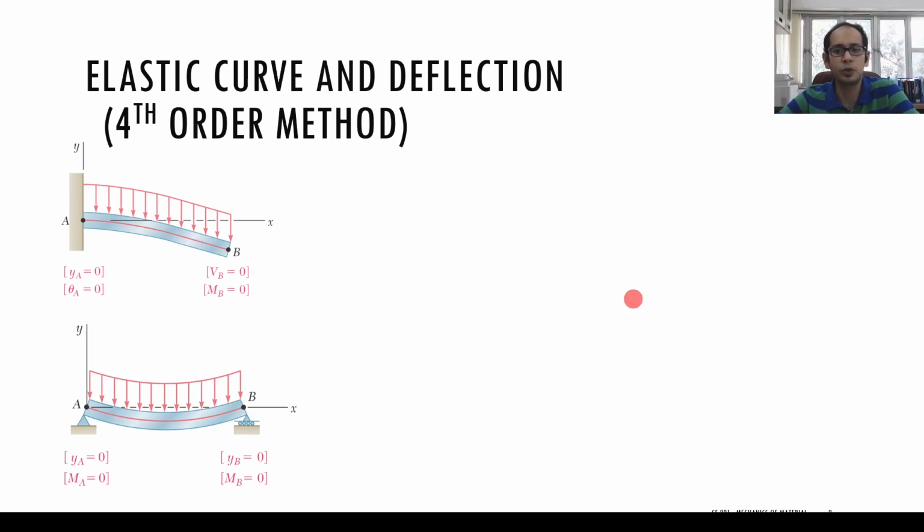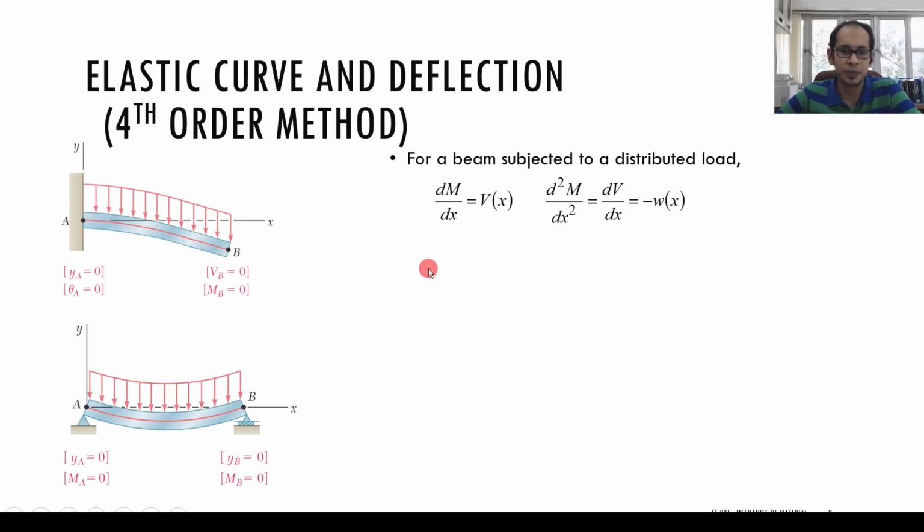if you take the fourth order derivative of your deflection, that becomes equal to the load. And let's see how that happens. But as I said, once you start to integrate the fourth order equation, if you integrate it twice, you end up with d square y by dx square, which eventually boils down to the second order method. So if you have, say, beams, for example, here with a uniformly distributed load and so on, and we know